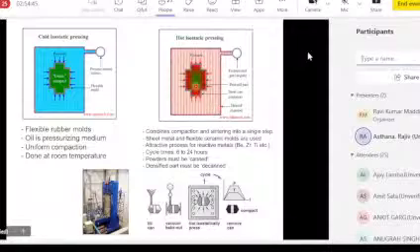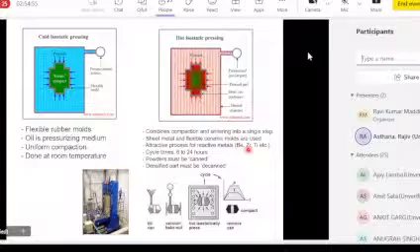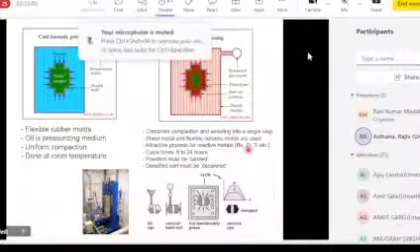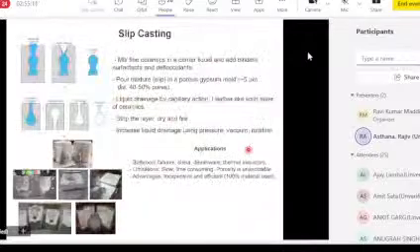So heating and pressing are combined. This process is good for reactive metals, things like beryllium, zirconium, titanium, anything that will contaminate because of heating in atmosphere. By combining pressing and sintering, you get higher quality parts. So cold isostatic and hot isostatic are two other pressing processes.